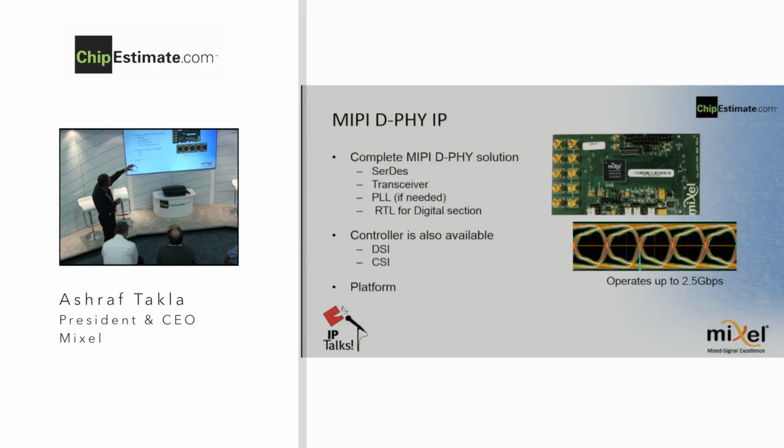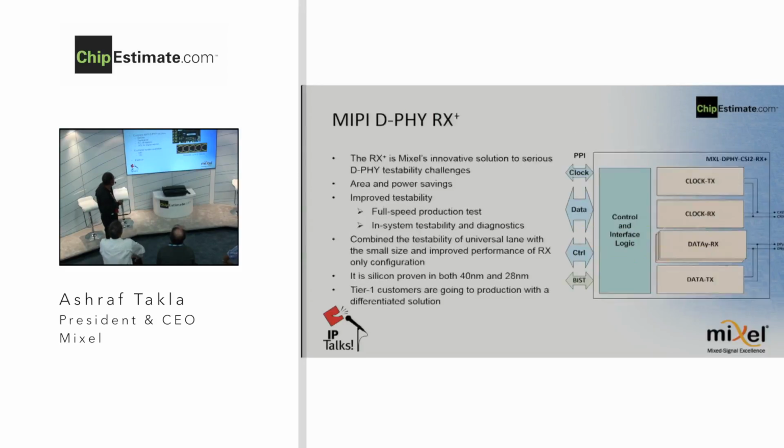This is the board with our test chip that I was talking about. We provide the whole complete solution, including the PHY and the controller. It supports CSI and DSI, which are the most common uses for the D-PHY today. So this particular PHY supports 2.5 gig operation. This is a new configuration.